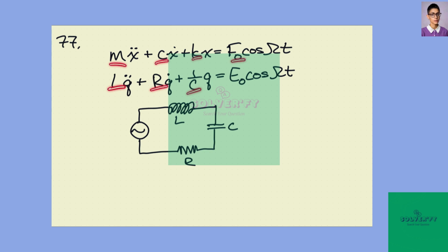So this would be the equivalent electrical circuit that would behave like this mechanical system does if you had these values all proportional. Again, you would wind up scaling these, because here you divide through by M, here you divide through by L, and so for a given inductance, because again, capacitors are usually very small, and the magnitudes are usually quite different. But if you scale everything appropriately, you'll get the same response.